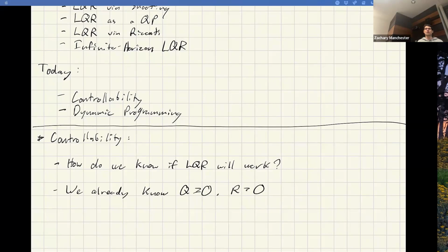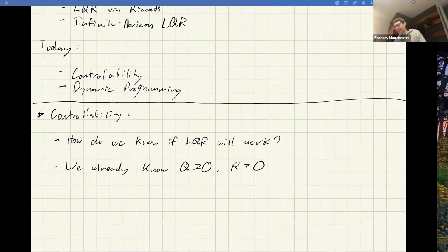In particular, we're going to get into convex MPC. If the constraints are convex, and in particular, if they're polytopic, you can say some things about this. But in general, it's super hard. And for general non-convex situations, which is honestly everything we really care about, obstacles are usually non-convex, right? So in that setting, it's actually quite hard to say general things. So yeah, sorry to disappoint you. But for right now, we're just talking about the dynamics.